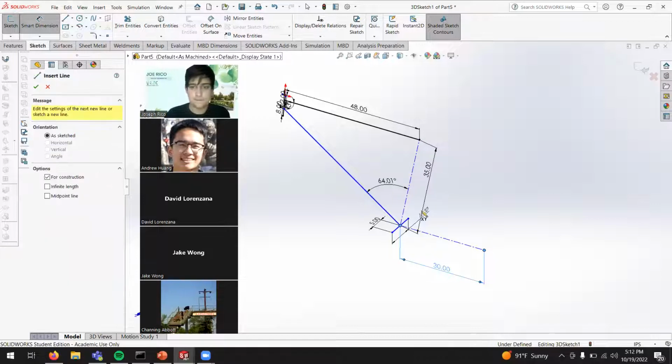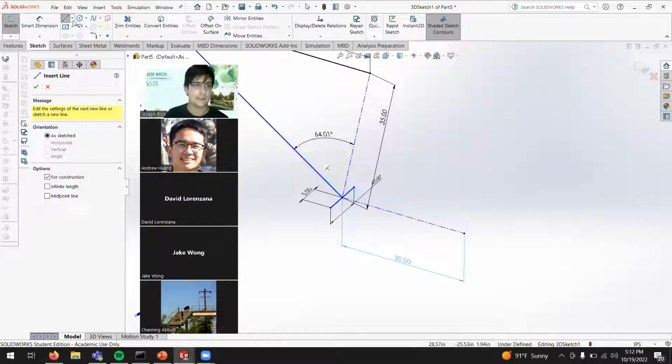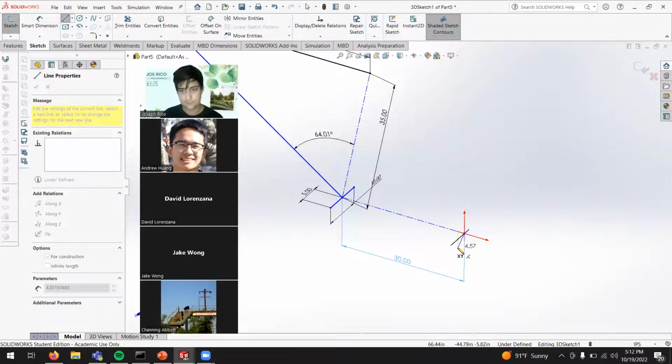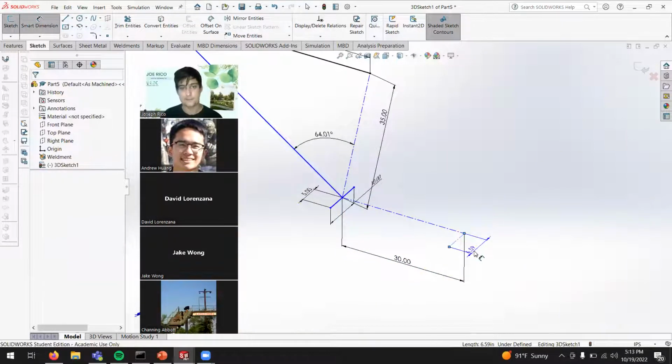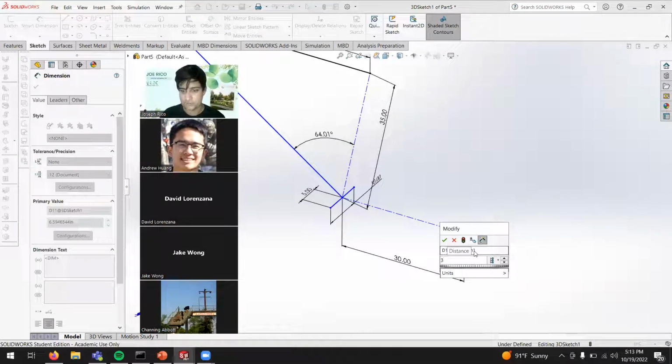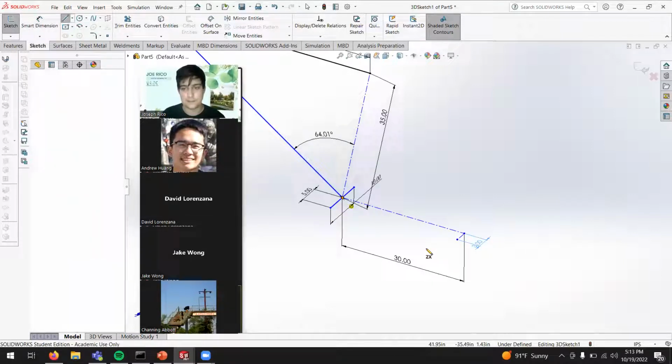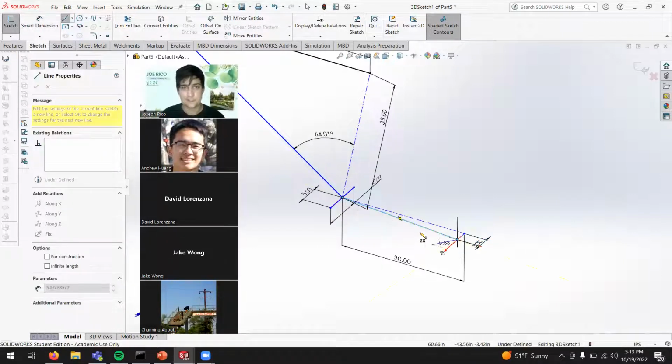Alrighty. And now what we could do is either you could input the angle directly, or you would know how far apart these back pieces are. And that's the assumption I'm working with. So what I'm going to say is that using a construction line, maybe to make space for all the bike stuff that goes in there. Again, we're going to use tab to change planes. For all the bike stuff in there, maybe it is a total of 6 inches apart. So I'll make this one 3 inches. Like that. And then using those two lines, we could connect it with an actual line out to there.